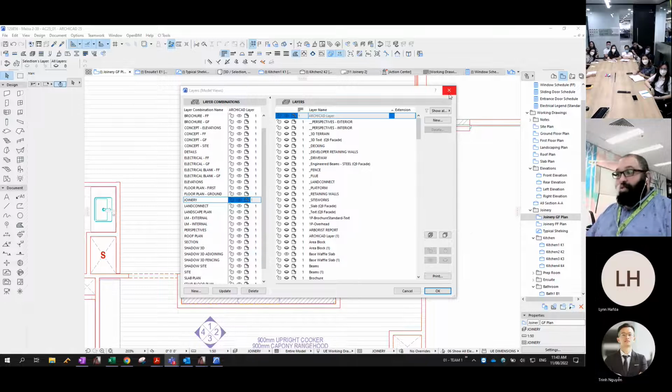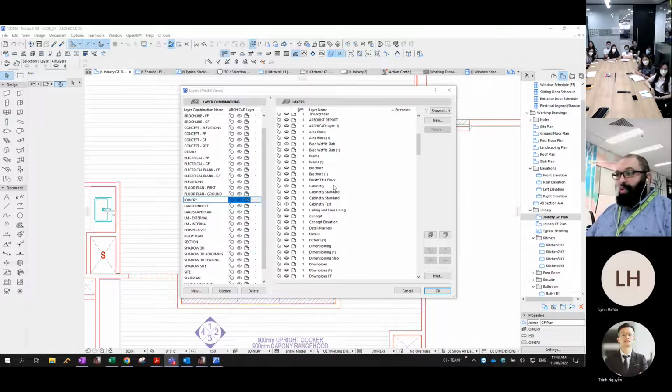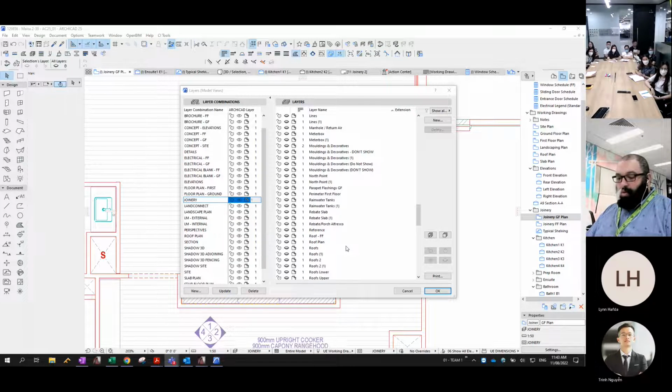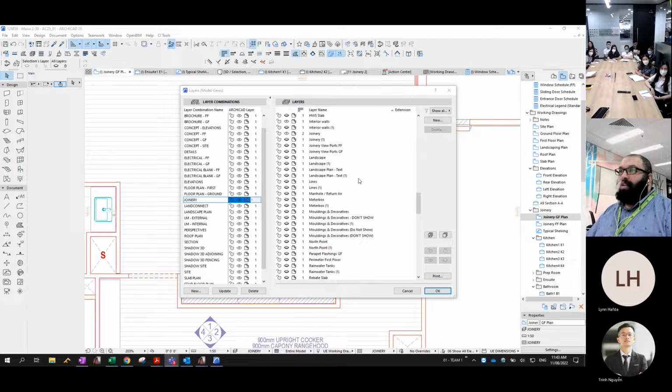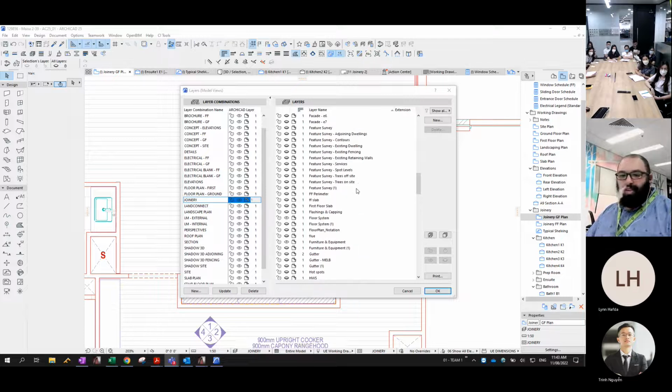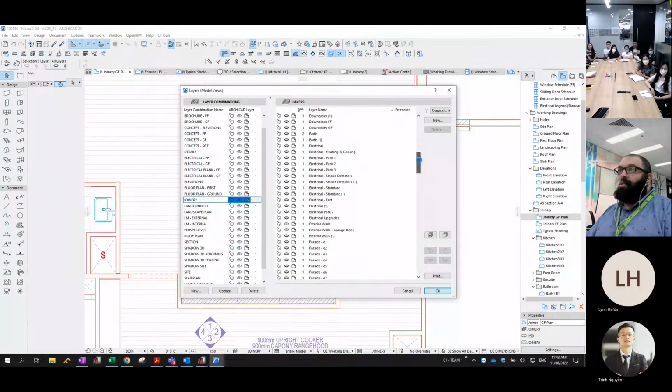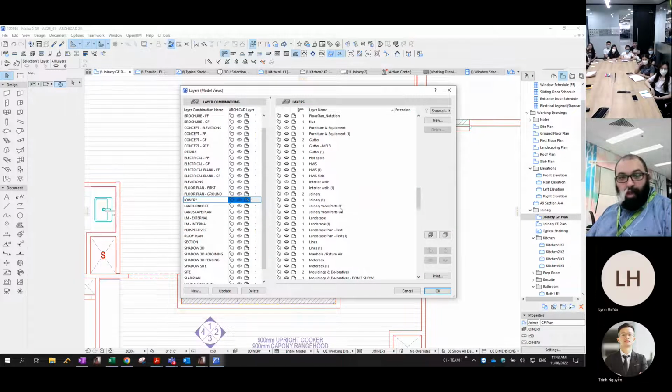When you need to draw an additional internal elevation, we'll start off by turning on the relevant layers. So for 8 homes masters, you'll have your internal elevation marker. For internal elevations, you wouldn't really need to draw any new internals. This is mainly for Urban Edge. For some of the newer masters, they will be on a joinery viewport elevation layer. So we'll turn on the joinery viewport for ground floor, and we'll turn this on.